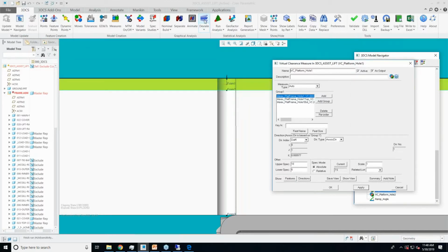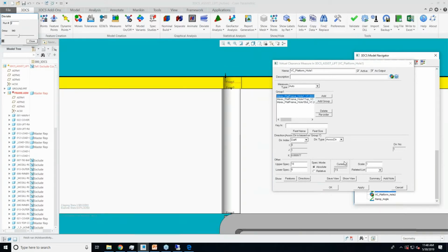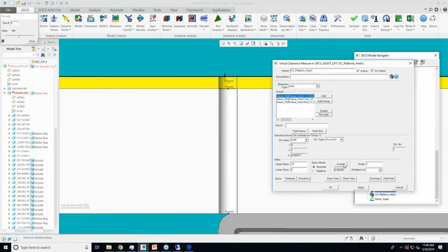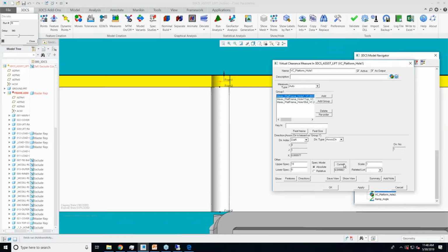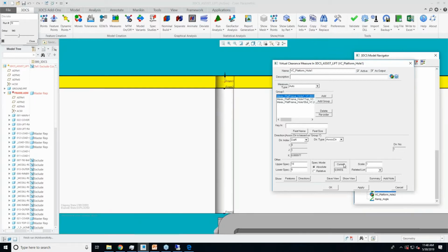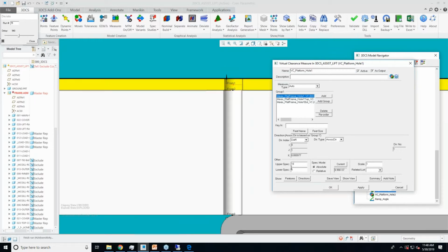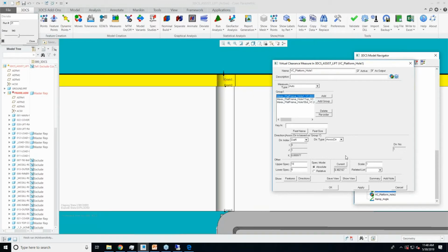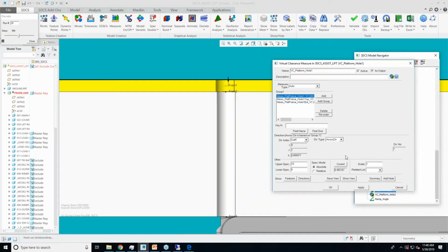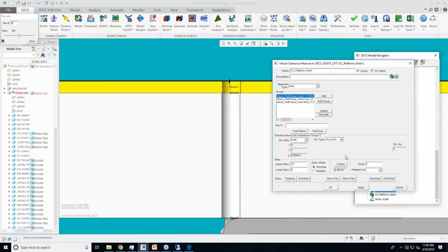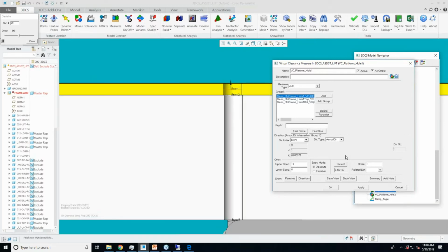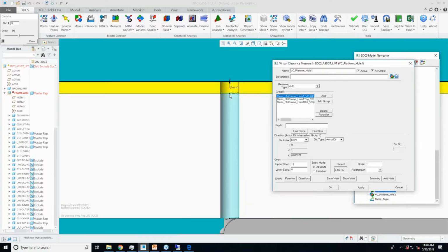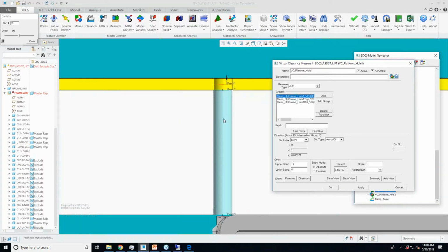Now if I deviate and we select this current button on each build, we should see this number drop below 7.5 as the positions of those holes change, and also the sizes of those holes change. But we want to make sure that it stays above that 6 number, which is our target. It's really cool because you can see the yellow wiggling relative to the white up at the top, due to tolerances and moves. Yep, assembly variation.